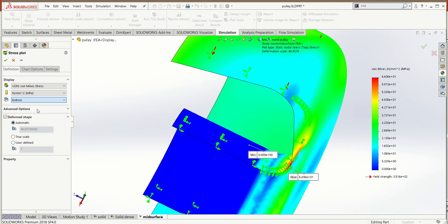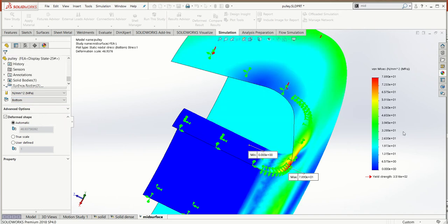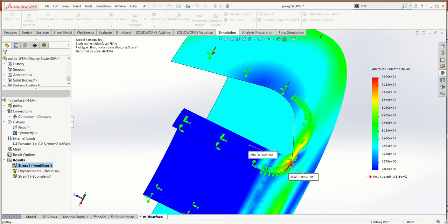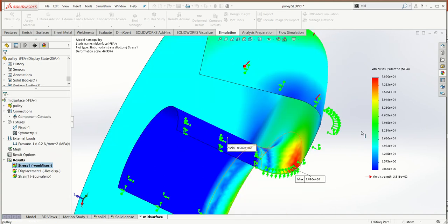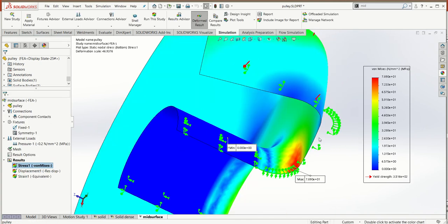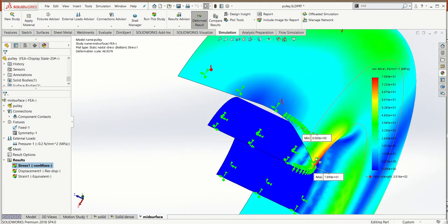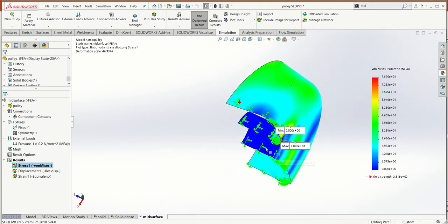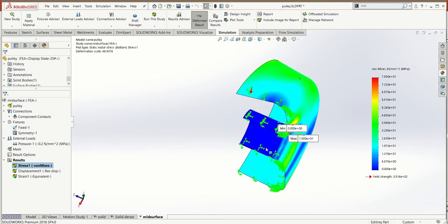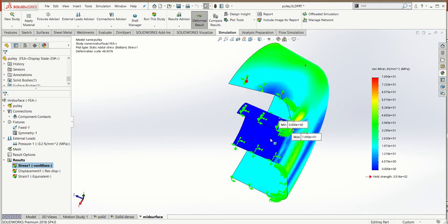So if you want to see the bottom stresses or inside surface stresses, then I will select the bottom, and here you can see the bottom is the inside faces values. So here you can see 78, which in solid is around 87, and for outside it's around 64. Means you can easily converge that much amount of result with the help of shell element.